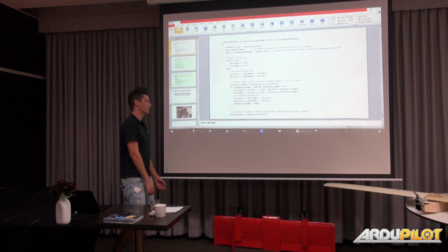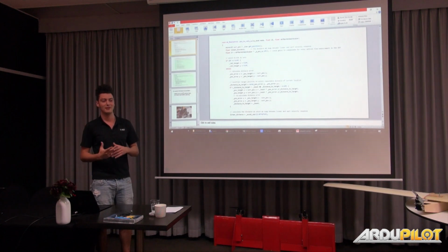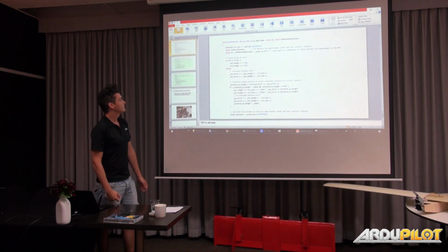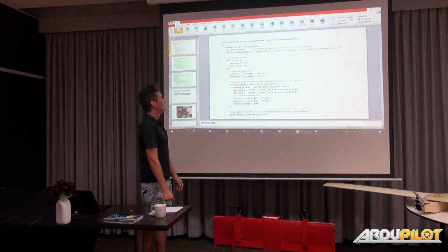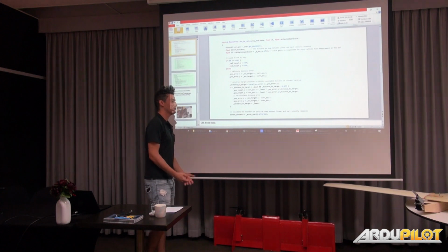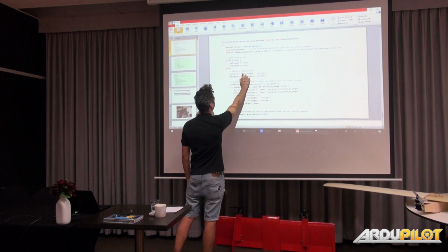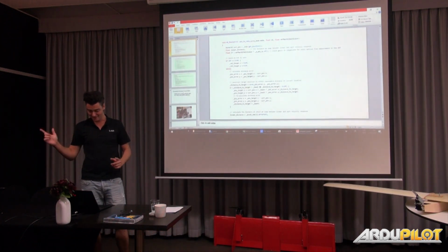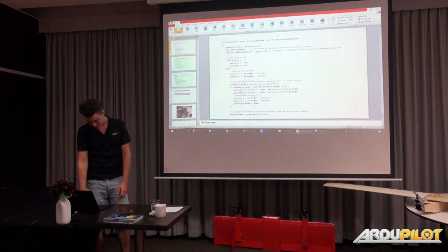Also, I've been thinking about another way. Maybe you guys use loiter mode to stay stable, so maybe I can use that feature and incorporate the LiDAR measurement to make my drone stable. So I've come across this pos to rate XY. Maybe you're familiar with it. So I have a position error, so I need to tweak the code to have my position error here. Okay, where do you take this one? And I'm equipped with my Notepad++, looking for functions and which one is calling which one, and sometimes it works.